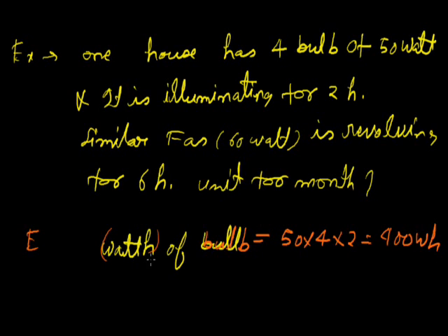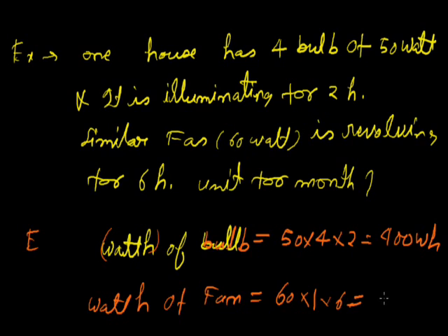Similarly, watt hours of the fan is equal to 60 into 1, as 1 fan is revolving, into 6 hours, so 6 sixes are 36, so 360 watt hours.